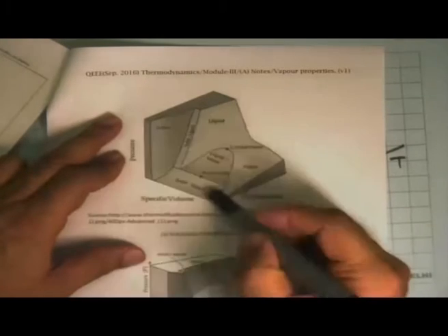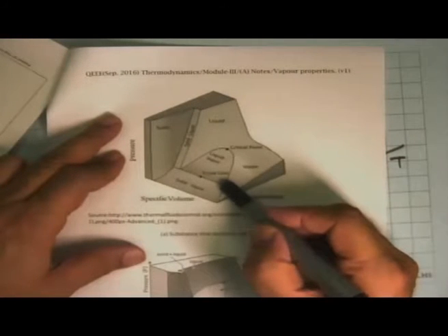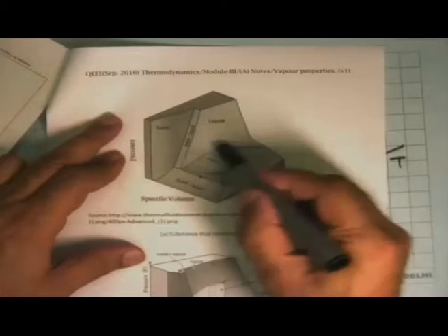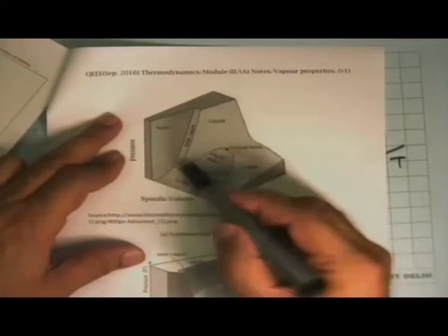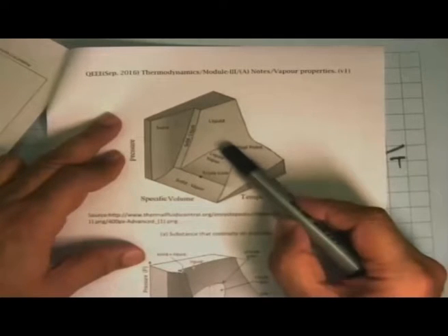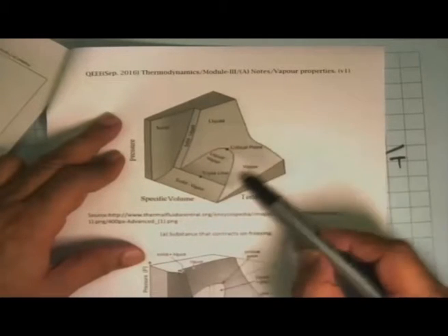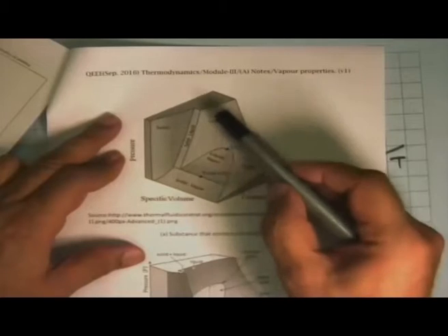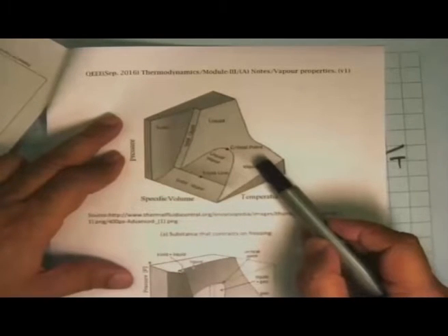So we have stacked up those curves one over the other and joined them by a three-dimensional surface. So you get an inclined surface which is the solid vapor phase, triple line, a critical point which has this shape, and as we go up and keep taking slices, this TV diagram became 0, and beyond that is this surface where it's liquid, dense liquid, and this side is superheated vapor.